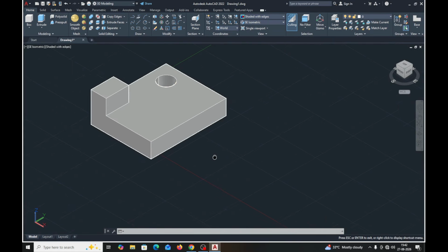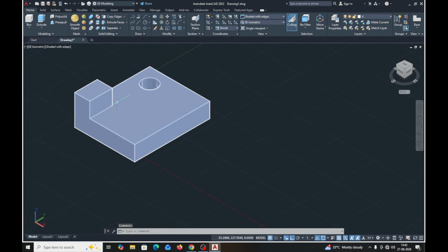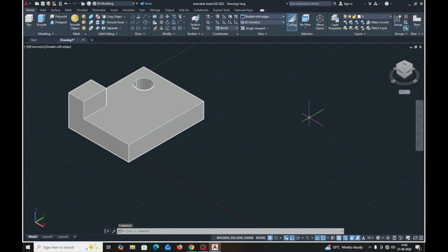Okay, suppose you face any problem creating the model here on the surface, you can also create it in the empty space on the working plane. It becomes easy to make the model in the empty space, and later you can shift it here. How? Suppose this direction is along the x-axis, say 50 mm.